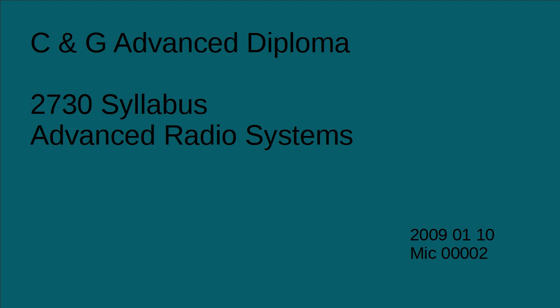So there are two categories: line type, aperture type. Line type collects the voltage from the electric field in the sky. Aperture type collects power from the power density in the sky. That is why in our last example we calculated electric field as well as power density, because depending on the receiving antenna, one or the other is becoming important.